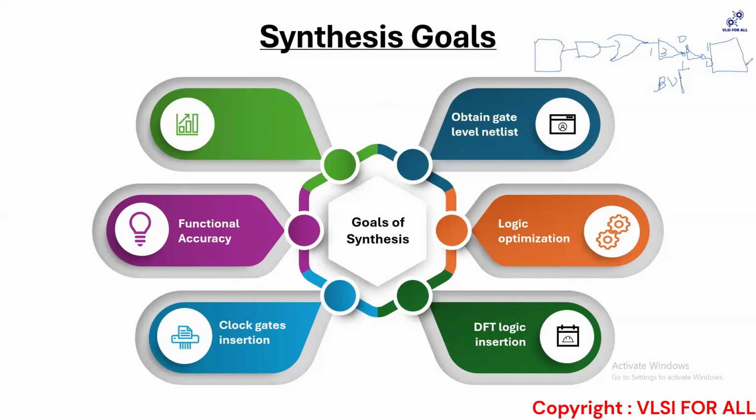Okay, because what happened is you made this blunder, and I'm saying this from a very small perspective, and without checking the LEC you passed it on to the PNR team. The PNR team takes it forward to the routing and the complete intention of the design has itself changed, right? Because what the PNR folks will do is they will check with your netlist.